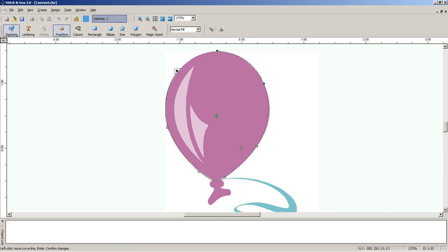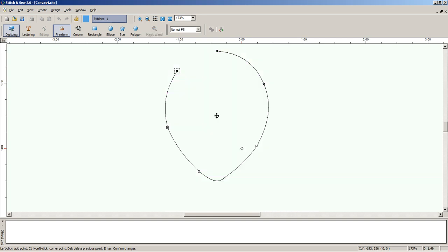So we've cleaned up our curve, and then as we get to the last point here, do not follow your instincts to try and set the last point on top of the original point. Leave it a little bit open like this. We'll press the L button to highlight the shape that we're doing, and to close the curve, press the 0 key. So press 0 and see how those two ends join. Now we're ready to digitize or fill this in with stitching.